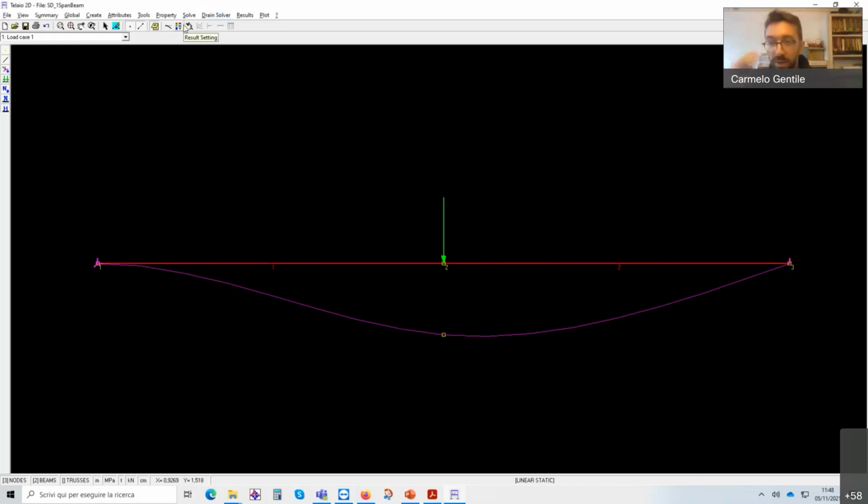So these are all the checks that you should be able to do also when solving a structure by hand computation. Once you have drawn the bending moment, the shear force, the axial force, now I put my pen on the table, I just watch the drawing and I try to understand if it makes sense. Obviously, since it is all computer based, it makes sense. The point is, is it what I asked him?